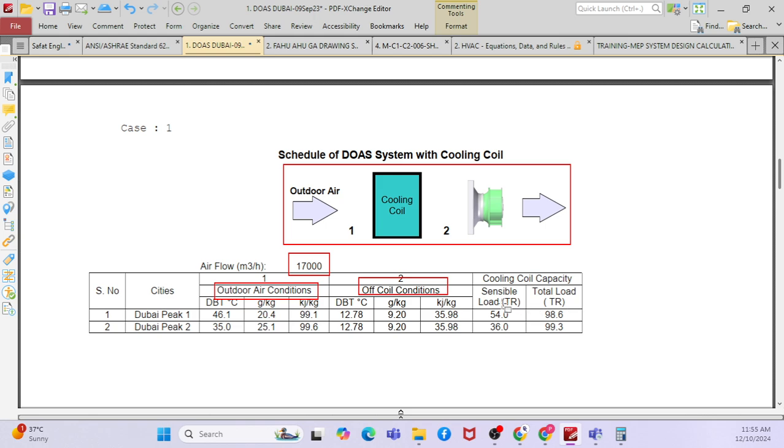So to calculate sensible load, you go to that equation. To find out sensible load, you need to know the delta T. CFM you already know, you calculated. So if you know these two values, you can calculate the total sensible load. Yes, CFM, how do we calculate? That is based on the ASHRAE standard 62.1. That is what we saw last week. Based on the ASHRAE flow rate, yes.